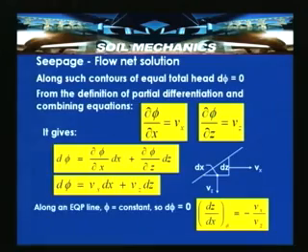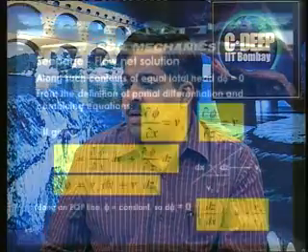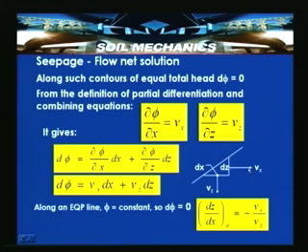So, dx into 1 is the area over which the flow is occurring. Vz and Vx are the velocities in the z direction and x direction. So, the slope is given by dz by dx of the potential line as minus Vx by Vz, where dz and dx are the small lengths of the element under consideration.